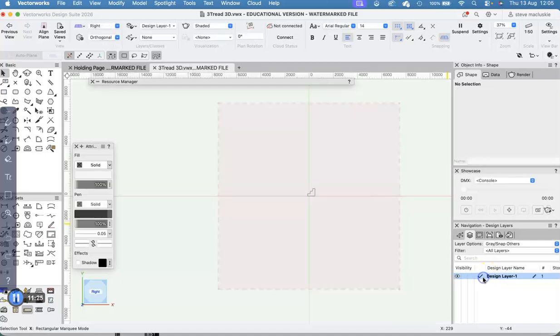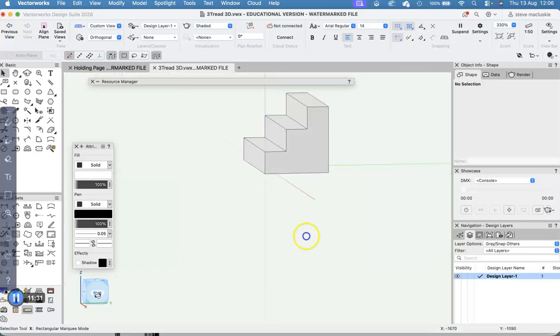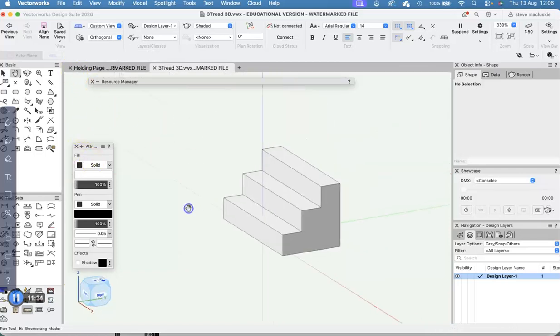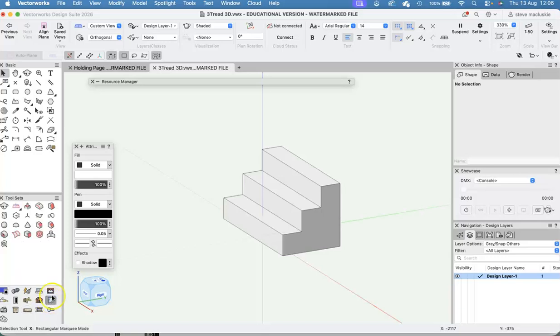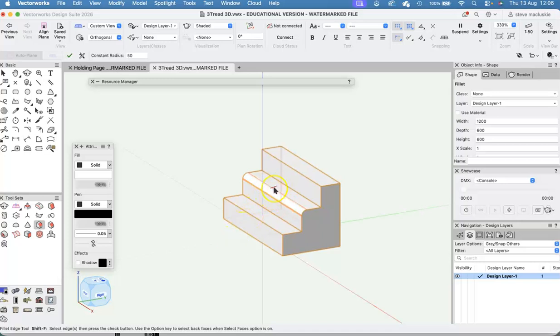As a little demonstration, if I go back into the design layer again, into this thread, I'll just spin around a little bit using that tool that I've still not quite got used to yet. And again, I need to move my screencasting tools. They're all underneath all of this stuff. There's my 3D modeling there, chamfered edge, or fillet edge. Fillet edge, we'll call it fillet edge. We'll do a radius of 50. So we'll just do a little rounded nose on the front of that thread, the middle thread there. It's got a rounded nose on it.